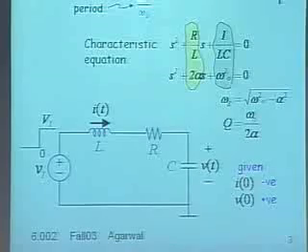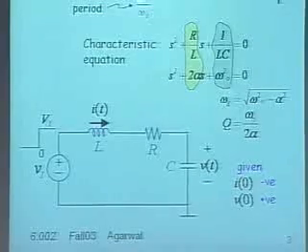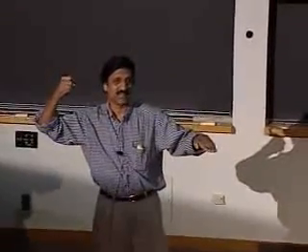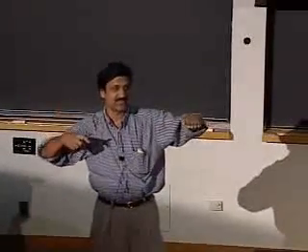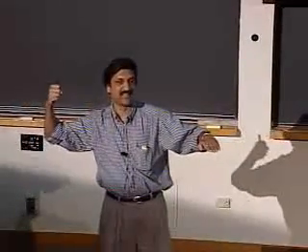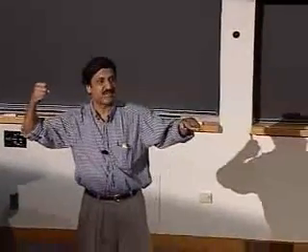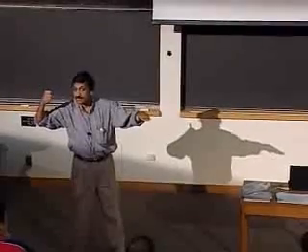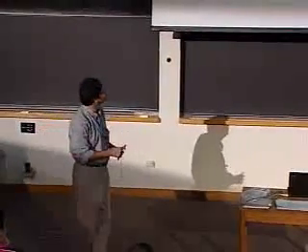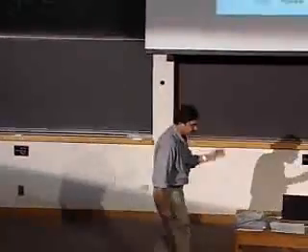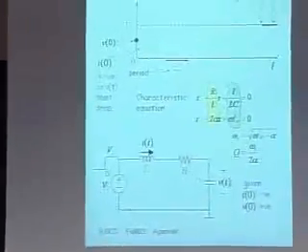So the capacitor has a voltage here, that's V0, and the inductor is yanking the current in that direction. So what happens to the capacitor? What should happen to the capacitor voltage initially? If I'm at V0 and someone is yanking current out, at least initially in that direction, what should the initial dynamics of the capacitor voltage look like? It should drop. Which means that if the initial current is being pulled in that direction, the capacitor voltage must droop to begin with. Completely through intuition, no math here.